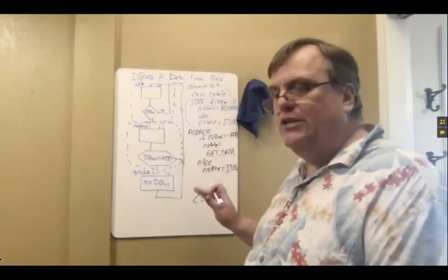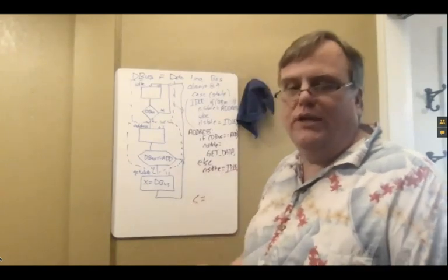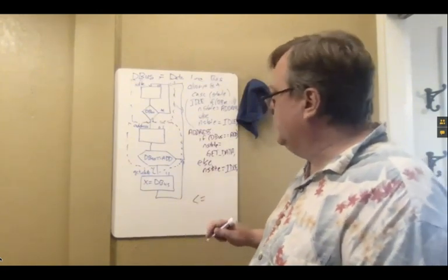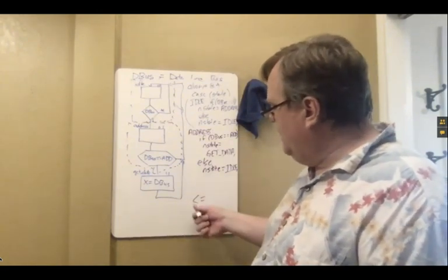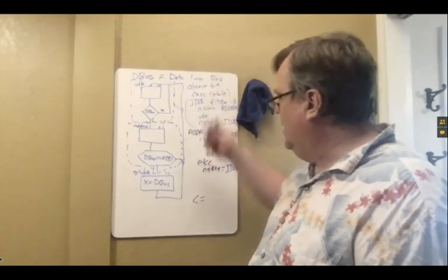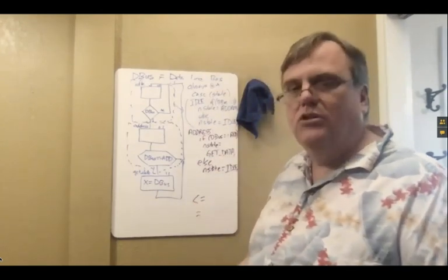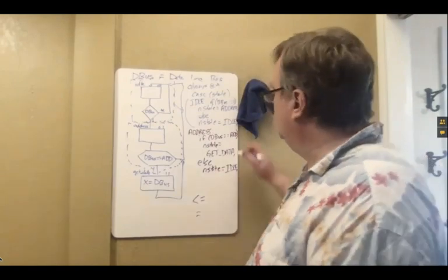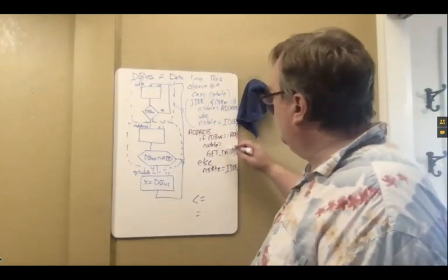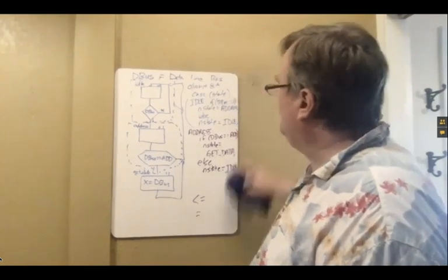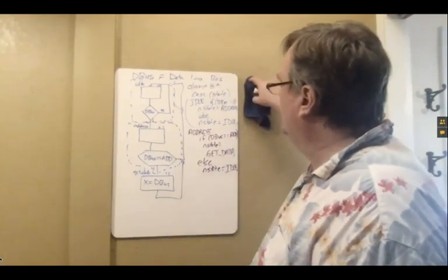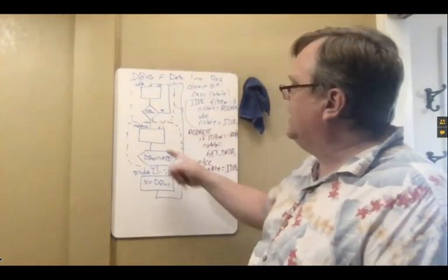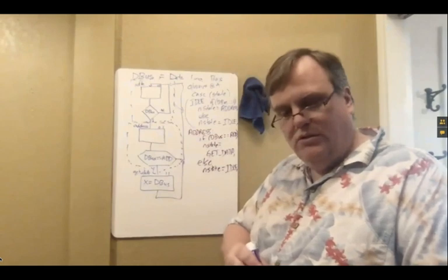If you follow this convention, you're pretty much always safe. So this is designed to be a very safe convention. So just think, if it's a flip-flop, use non-blocking. If it's combinational, use blocking. That's the basic rule whenever you're dealing with it. So you notice I'm following the convention all the way. Right. But I've now got, again, only one if statement inside address.